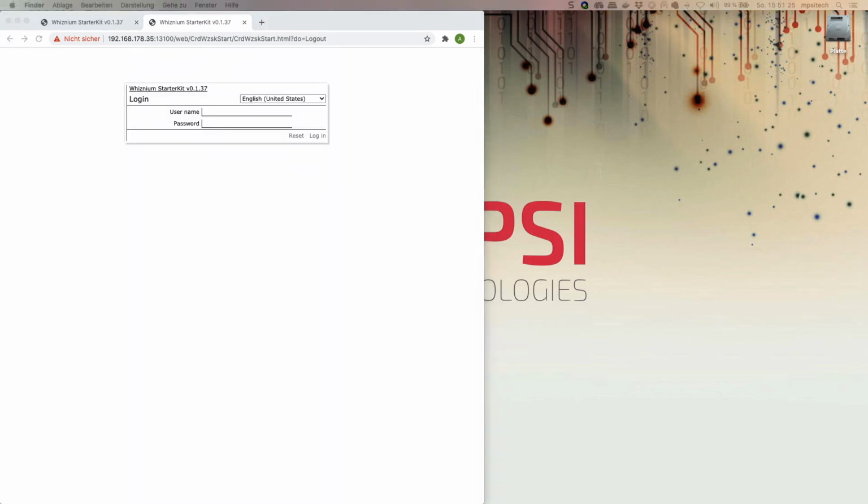Before finishing this episode, I would like to make some remarks on the FPGA-based starter kit version, which I also have here next to me on the table. So, the functionality is the same and the software is the same, only that the relevant image processing algorithms run within the programmable logic. In fact, compared to the embedded Linux version, the camera is now not wired up to the ARM processing cores via MIPI, but it's connected to the programmable logic with a digital parallel interface.